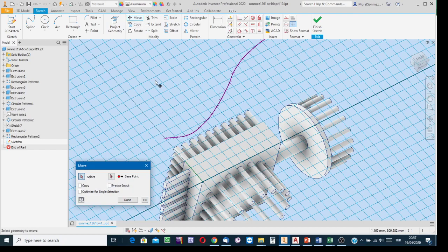Click on this button and indicate the curve in the move process. Sorry, the selection button is on. Indicate the curve at any point with a click, and then base point. Click on the base point indication button, indicate this terminal point, and then take the curve and locate it to the corner.